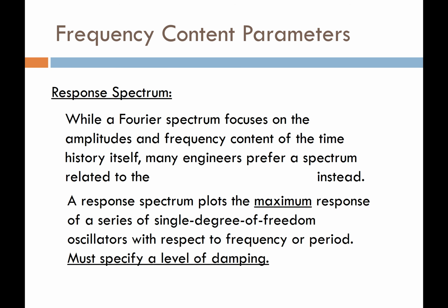Now, something that's similar to a Fourier spectrum, but a little different, is called a response spectrum. The Fourier spectrum is useful, but it focuses on the amplitudes and the frequency content of the time history, or the ground motion itself. And that's nice, that's the incoming ground motion, but we're a little more interested in what the response of a structure might be. And so engineers might want to know what the structural response would be to those time histories.